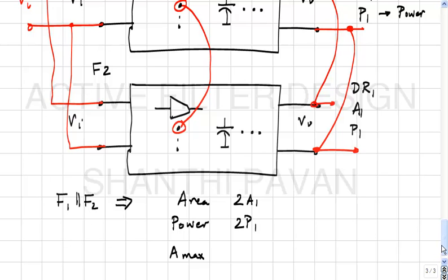Yes, please note that in fact it does not matter if F1 and F2 are linear networks or non-linear networks, as long as both of them are exactly identical and both are being driven by exactly the same input, then the corresponding node in F1 will always have exactly the same potential as the corresponding node in F2. So if I have a wire between those two corresponding nodes, no current will ever flow through them, right?